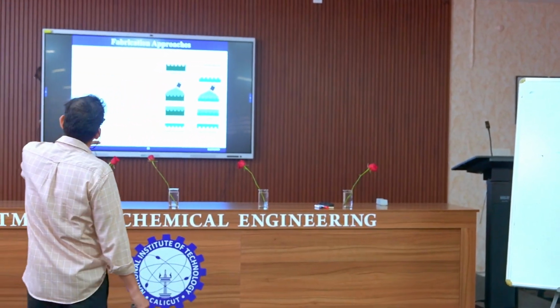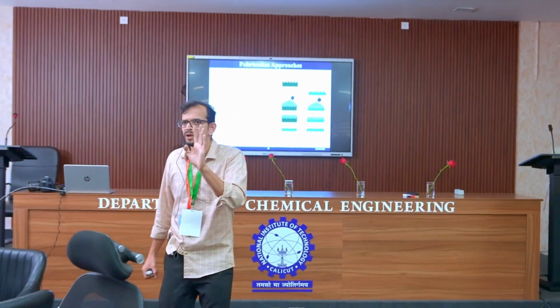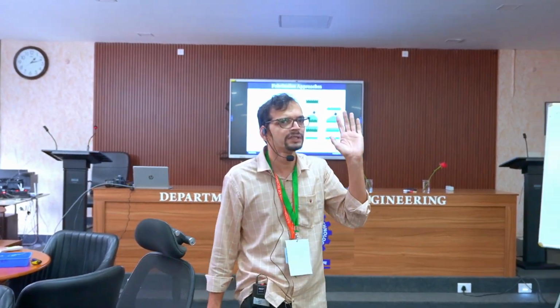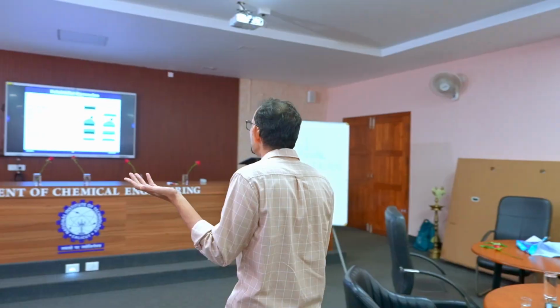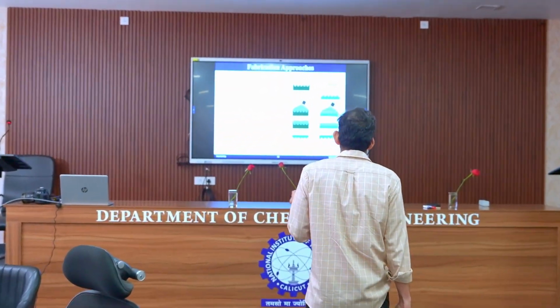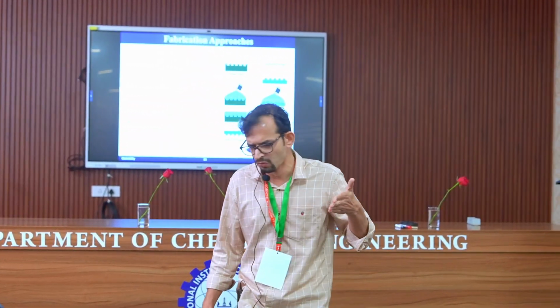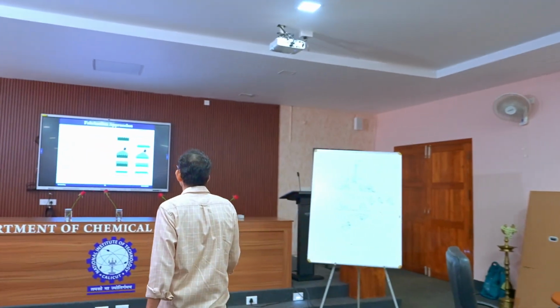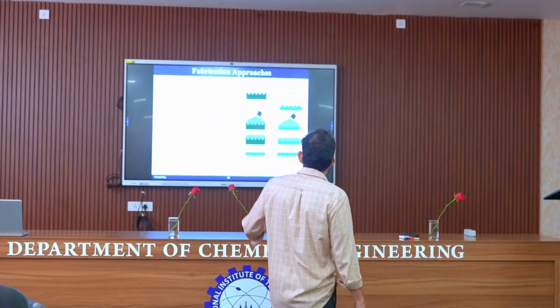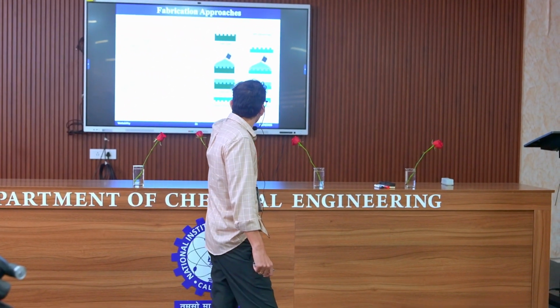Think about the first one, the lotus leaf. I want to make a number of lotus leaf copies without disturbing nature. That means I have to replicate it, that is the purpose. PDMS is the best friend for us, because it can cure and it can go even close to nanometer structures. Applying some vacuum, we can get rid of the bubbles and then heat it at a certain temperature, 80 or 70 degrees, and you can get the negative.